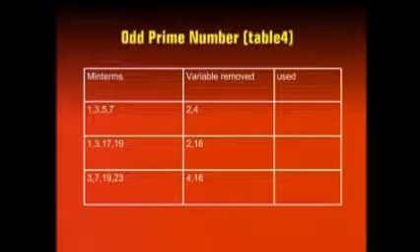There are 3 prime implicants in table 4 and 5 prime implicants in table 3. The 8 prime implicants are represented by the product terms A bar, C bar, D, E, A bar, C, D bar, E, B, C, D bar, E, A, C, D, E, A, B, C, E, A bar, B bar, E, B bar, C bar, E, and B bar, D, E.